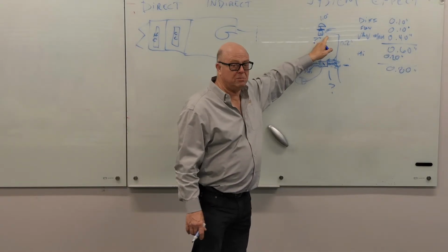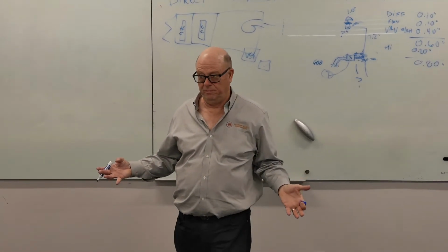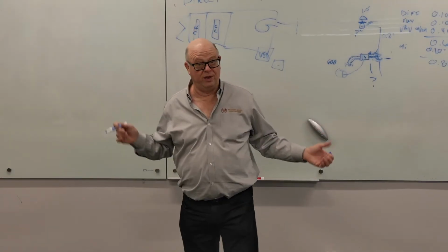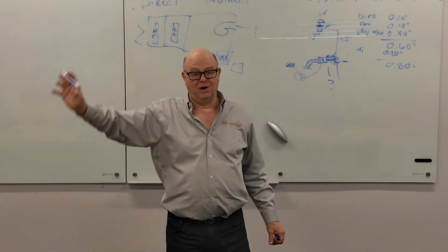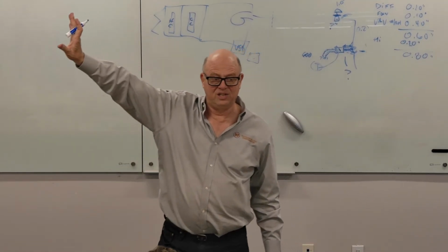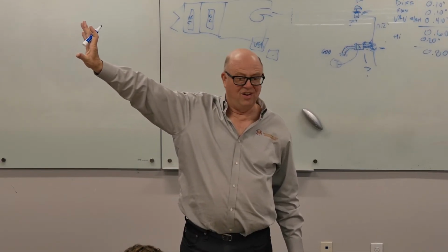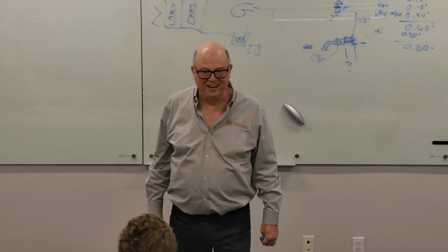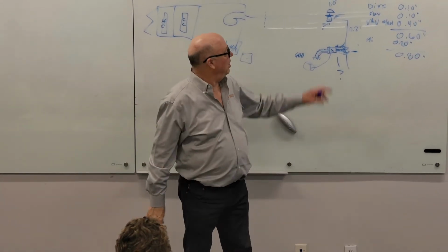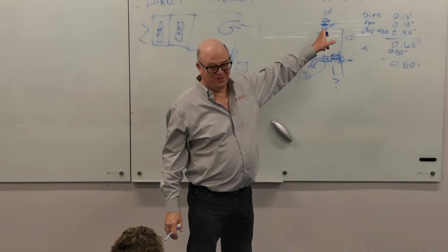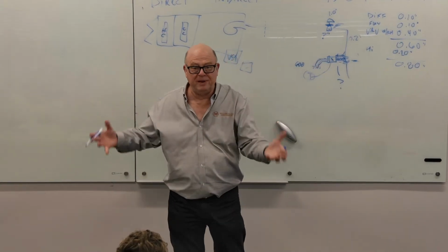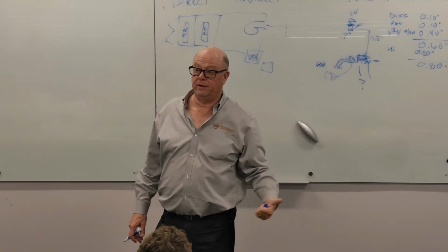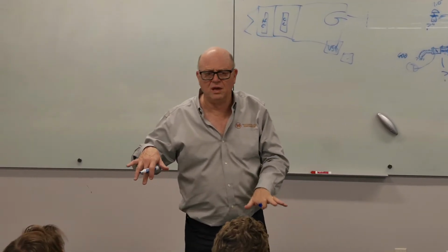This is an adjustable set point on the automation system. And let's say, on the other hand, we do a global thing, and all of the offices with the glass facing the sun are a couple degrees warmer than they should be, and the box is wide open. Okay, we aren't putting enough air into the duct now, are we? So now that same analysis can cause us to bump up the pressure that we're maintaining in the duct. It's kind of a dynamic thing.